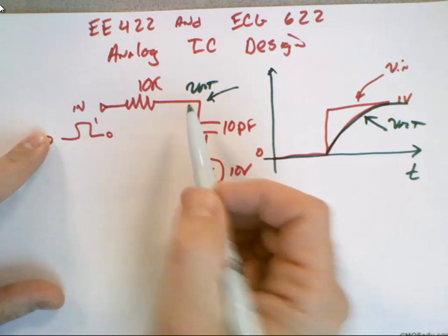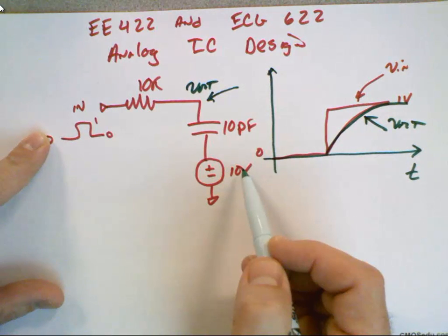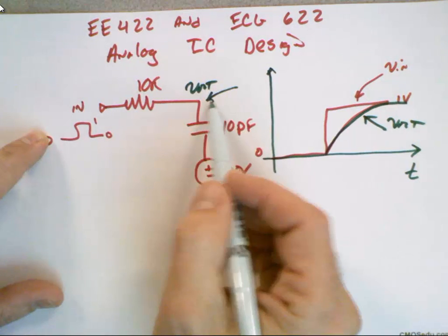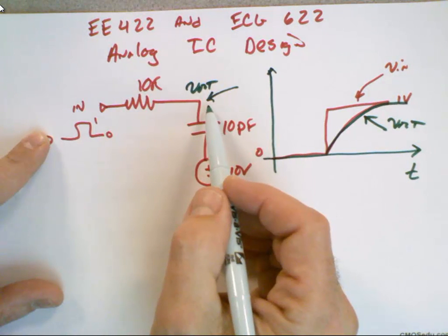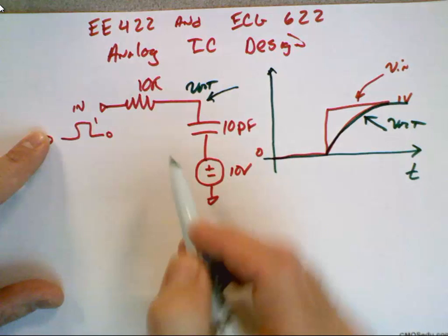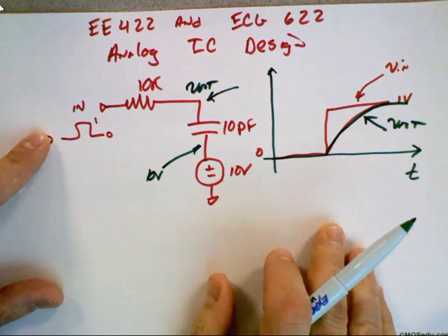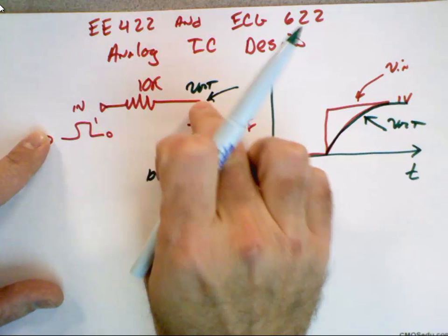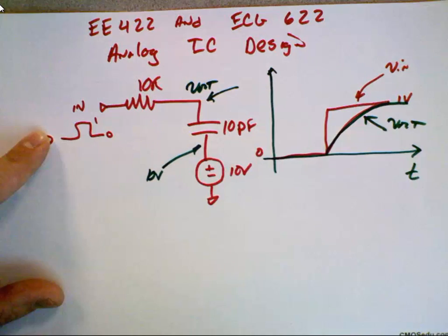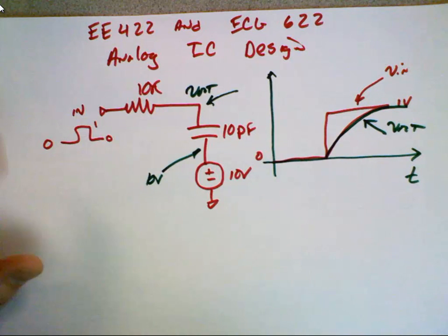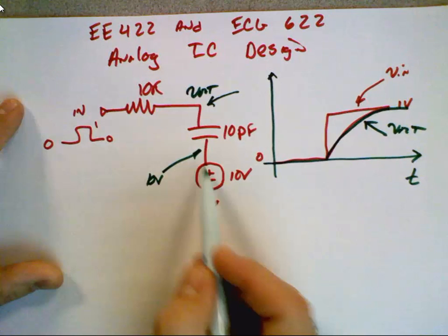Okay, so what just happens over here? What's the final voltage and why? So if I look at this, that's V out. It goes to 1 volt. So question, what if I change this to 90 volts? Does it affect anything over here? If this is 90 volts DC or 10 volts, this always stays at 10 volts, correct? Does it affect anything that's happening over here, even though I change that voltage? Now this is useful for your homework. Doesn't. It holds it right there at the same potential.